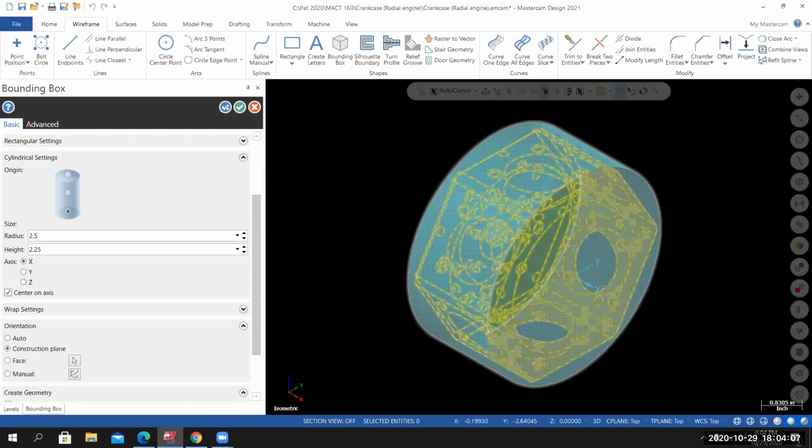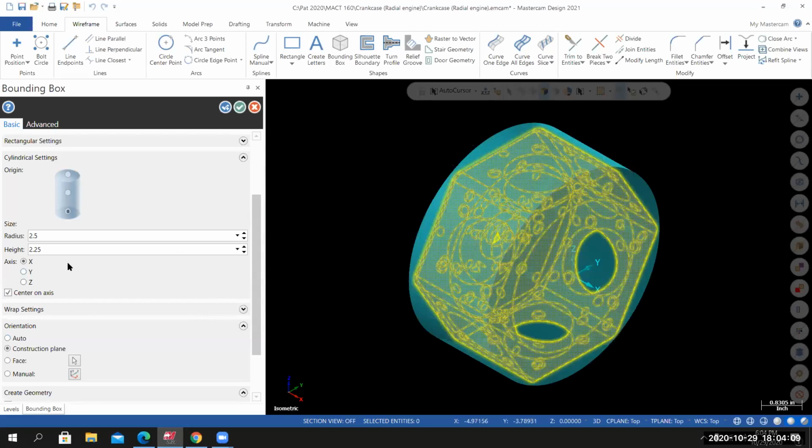From here, remember, we're going to make this from a 2.75 thick piece of material, or long piece of round bar. So I want to add 20 thousandths to this front face. That'll give us 20 thousandths to remove when we face the top of the part, and it'll give us a nice machined surface along this open face. So I'm going to select this surface. I'll hover my cursor over the arrow that appears. I'll type in 0.02, enter once, enter twice.